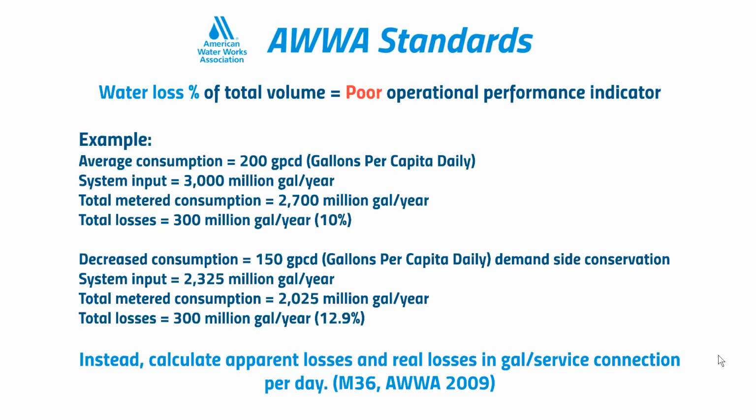So the AWWA has set standards. That graph allows you to create a very accurate picture considering all the other types of water loss. The AWWA water audit creates an accurate picture of your water loss, your unaccounted for water losses. In other words, your leaks.